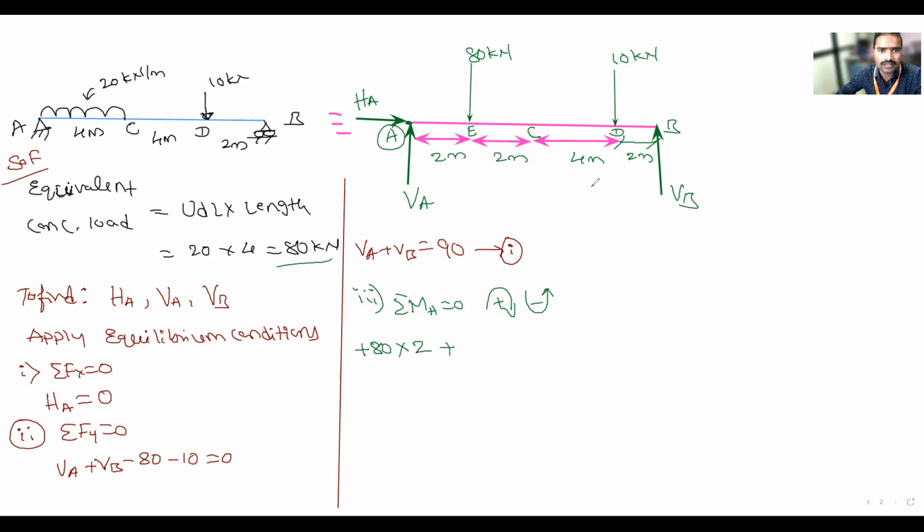Plus, again this 10 kilonewton. Is this 10 kilonewton rotating the beam clockwise or anti-clockwise? Clockwise, so plus I have written. What is the force? 10 kilonewton. What is the distance from A to B? 8 meters. Then, is there any other force?